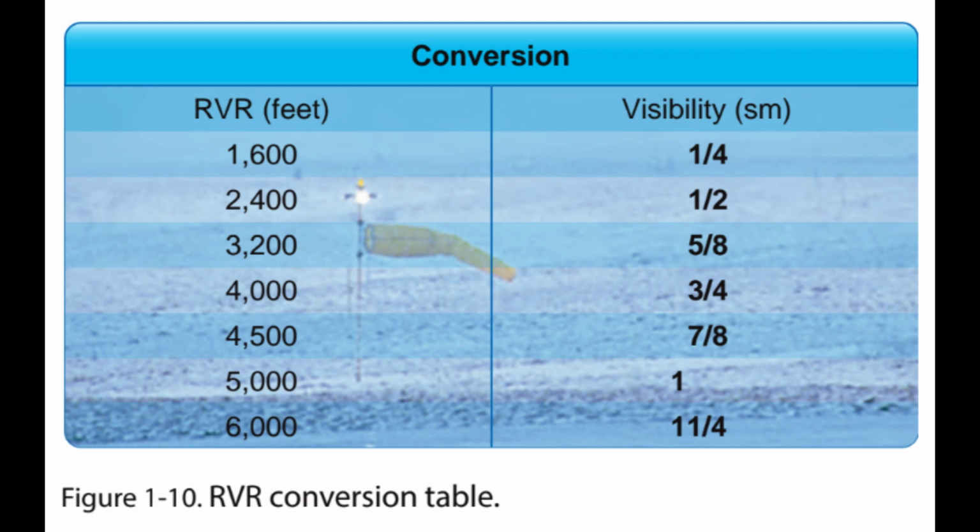RVR is the primary visibility measurement used by Part 121 and Part 135 operators with specific visibility reports and controlling values outlined in their respective OPSpecs. Under their OPSpecs agreements, the operator must have specific, current RVR reports, if available, to proceed with an instrument departure. OPSpecs also outline which visibility report is controlling in various departure scenarios.